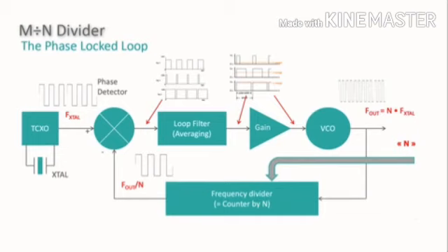First, let's talk about the phase detector. Not all phase detectors generate 0 volts at 0 phase difference. In this case, the phase detector produces a 50% duty cycle waveform when the divided VCO frequency and the crystal oscillator have the same frequency but are exactly 90 degrees out of phase. When the VCO runs faster than the crystal oscillator, the phase detector produces a duty cycle less than 50%, which slows down the VCO, which keeps the two signals exactly 90 degrees out of phase.